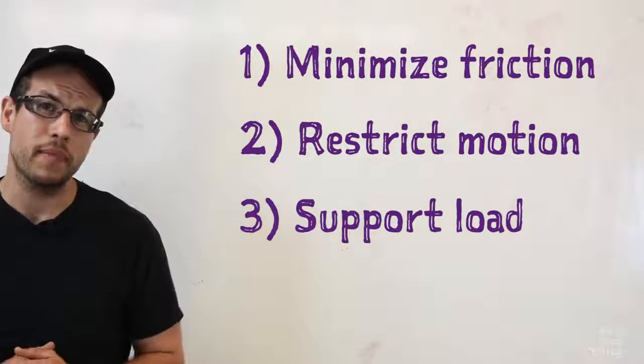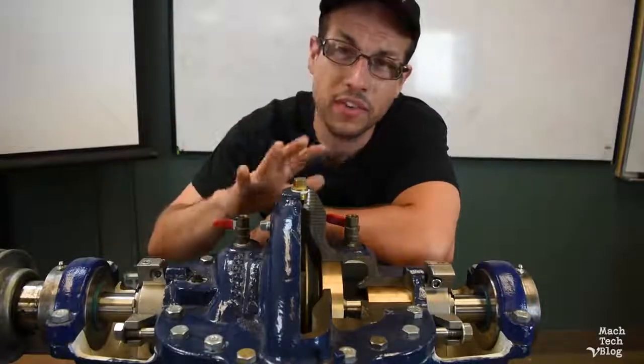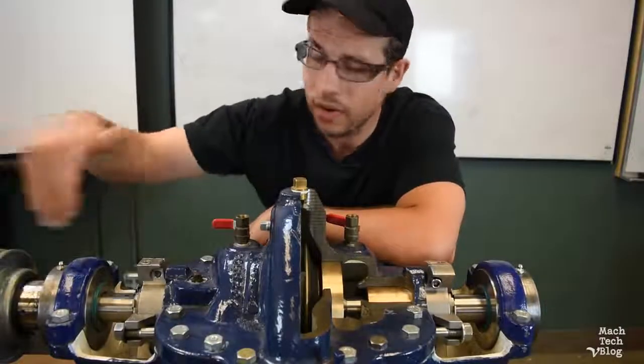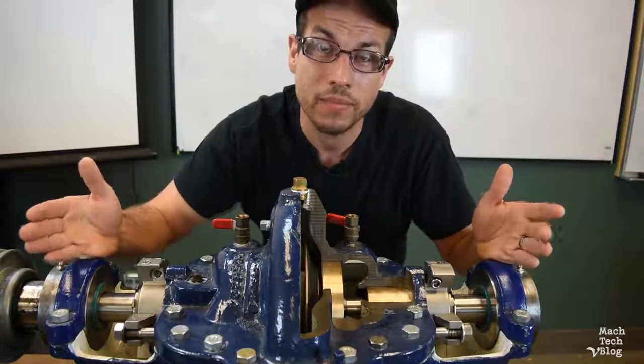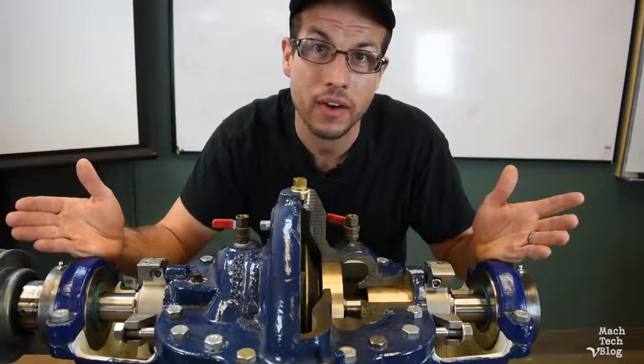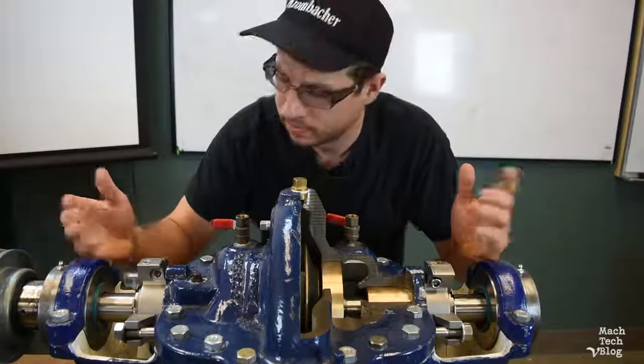Let me show you what I'm talking about. Hopefully you noticed by the way that this pump is set up. We have a stationary casing, and we have a rotating shaft that runs through it, and on either side we've got bearings. Notice the bearings usually come in pairs. Depending on the application, you could have more than 2, but you always need at least 2.